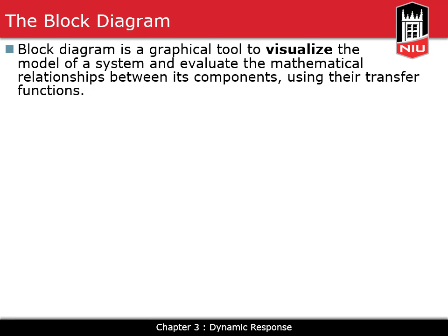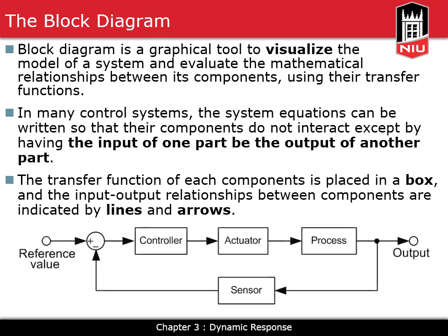So after going over some basics about Laplace transform, now we want to discuss the block diagrams. Block diagrams are a graphical tool to visualize the model of the system and evaluate the mathematical relationships between the components. The reason it's good is mostly because you can actually divide your entire system into smaller pieces, smaller blocks, and each of those blocks represents a component in the system.